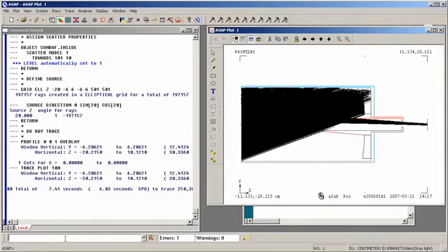If we want to actually see the distribution of light on the detector, we have to ask for it. We tell ASAP that we're only interested in the light on the detector. Consider only detector. We want a window whose vertical axis is Y and horizontal axis is X. And we'll set up the resolution for our calculation.